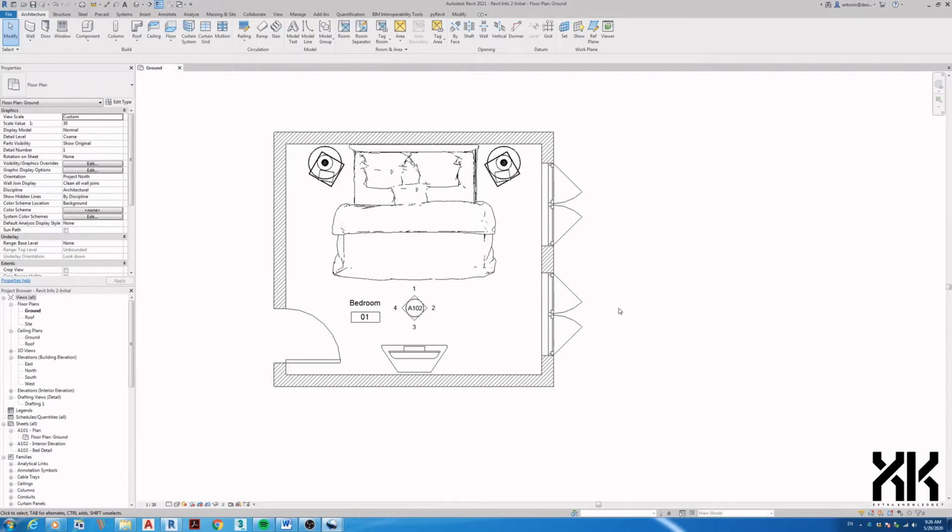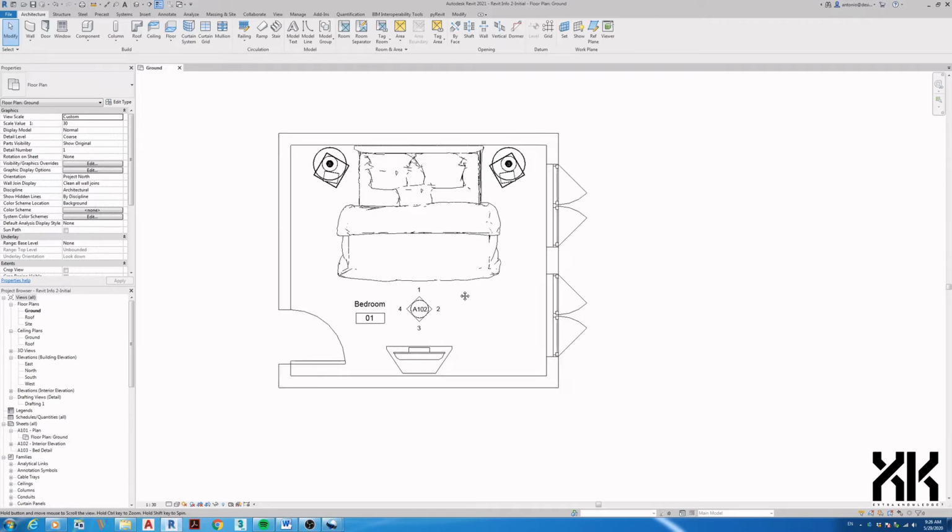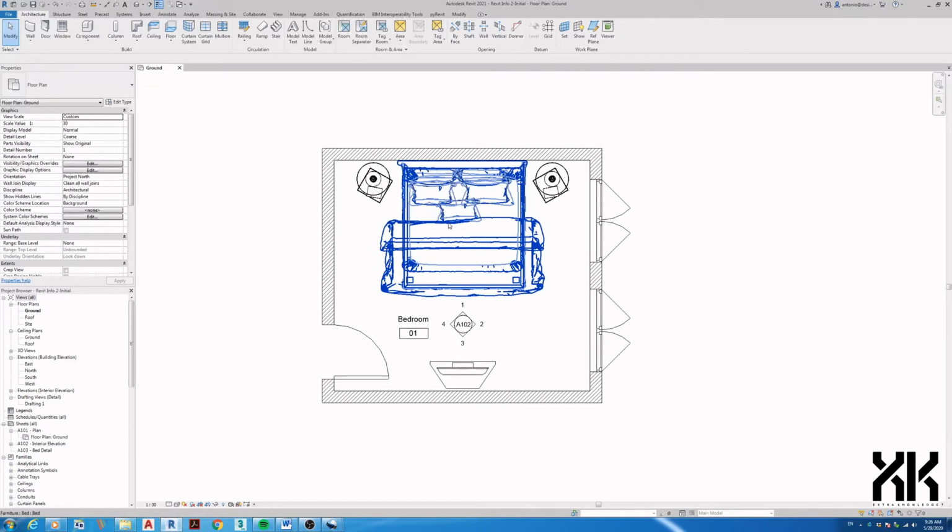As you can see, I opened the bedroom layout. In Revit, this is what we call the main model. Here is the step-by-step process to create your options. First, create design options, or just simply saying, name your options. Go to the status bar, click the design options button.